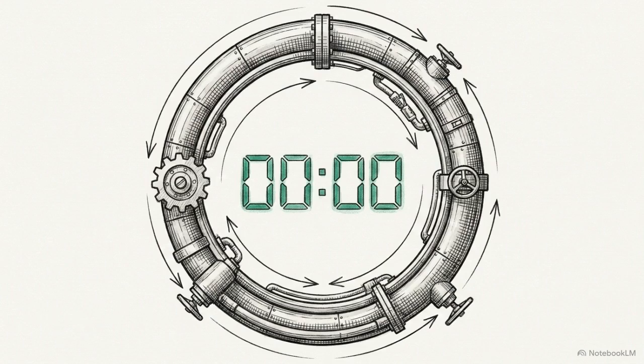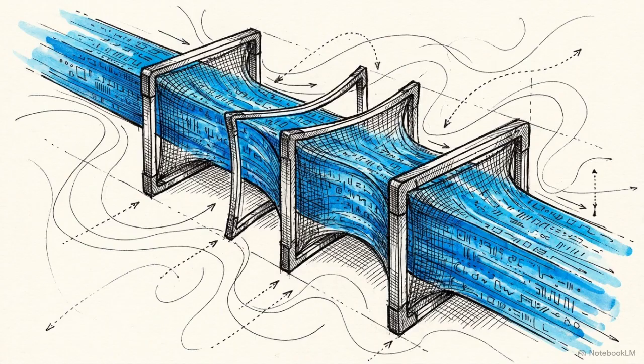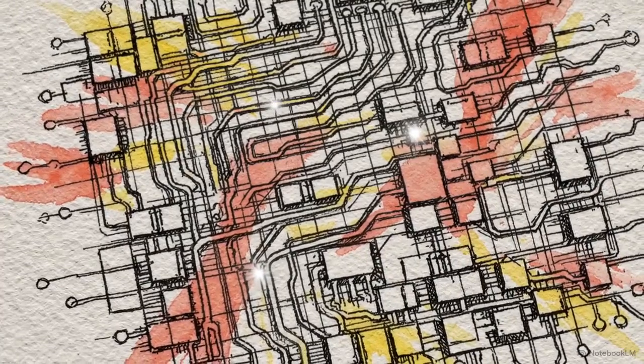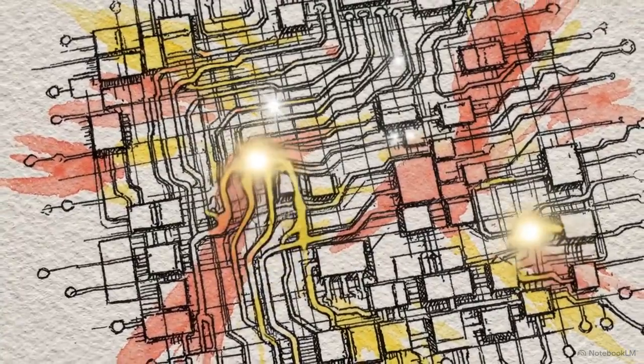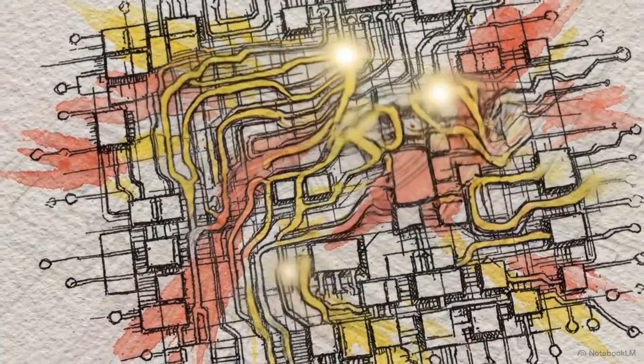Time borrowing proves that the synchronous clock edge does not have to be an absolute wall. By selectively reverting to simpler latch-based architectures, hardware designers stretch time across boundaries, absorb inherent sequencing delays, and squeeze maximum performance out of the silicon.